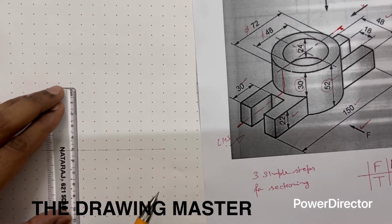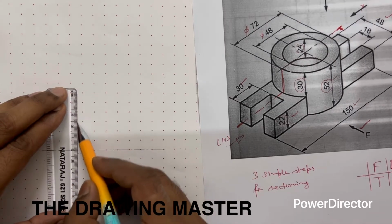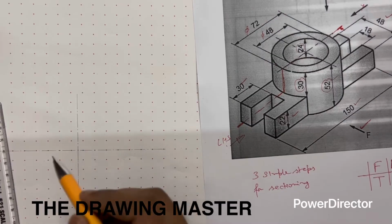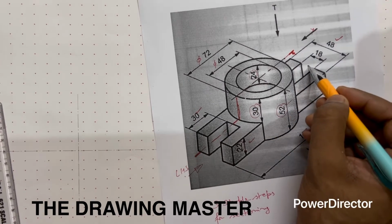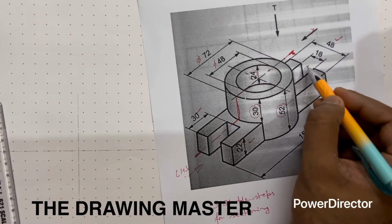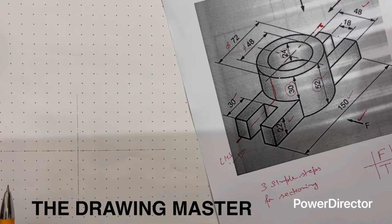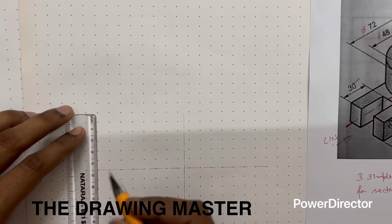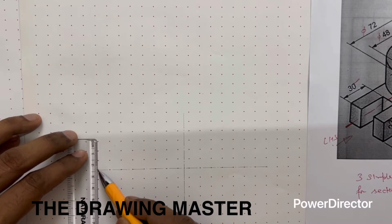We can draw the vertical center line also. Here will be the center of both the circles. Total length of the object is 150 and the width is given as 48 mm. Means if this is the center, 24 this side and 24 this side. For this 18 mm slot, 9 mm this side, 9 mm this side. So let's draw 24 upside and 24 downside. This total width is 48.